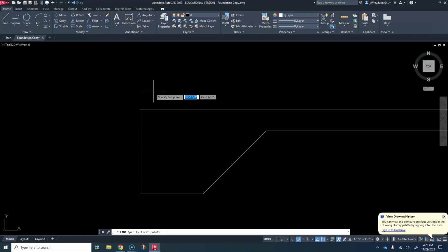The brick, I'm just going to go with a round number of 4 inches wide. So my brick is 4 inches wide. And then my airspace is going to be 1 inch. I'm specifying a 1 inch airspace on this brick wall. And then my sheathing, a lot of people use 1/2 inch sheathing, but I'm going to use 3/4. So I've got that 4 inch brick, 1 inch airspace. That's 5 inches plus 3/4 of an inch. That is 5 3/4 inches. So I'm going to hover right down here with my cursor, and I'm not going to click on anything.